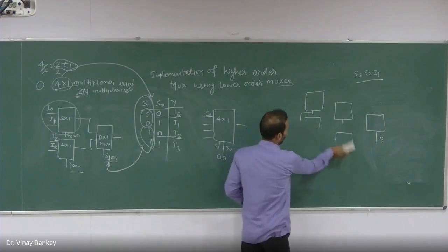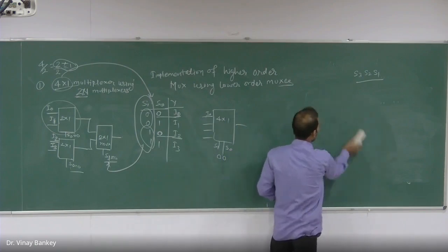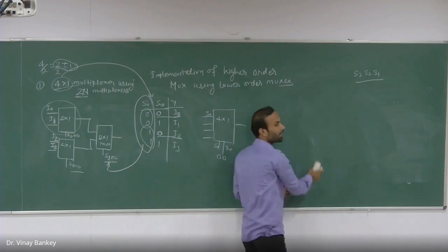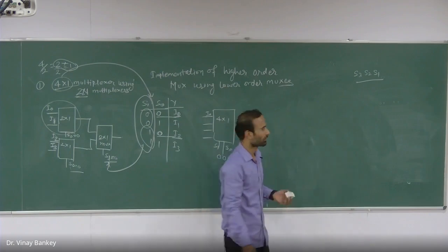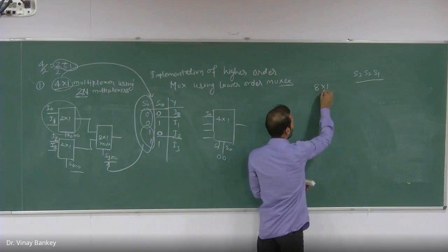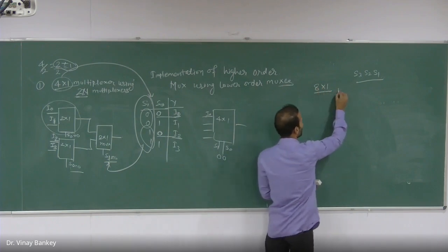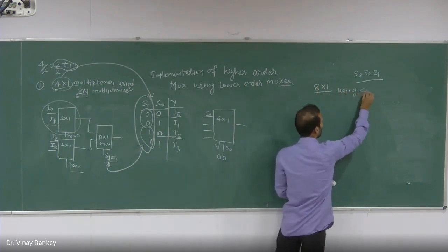Yes, actually it can be implemented, but using the enable input of the multiplexer. The question was, implement 8 cross 1 multiplexer using 4 cross 1 multiplexer.